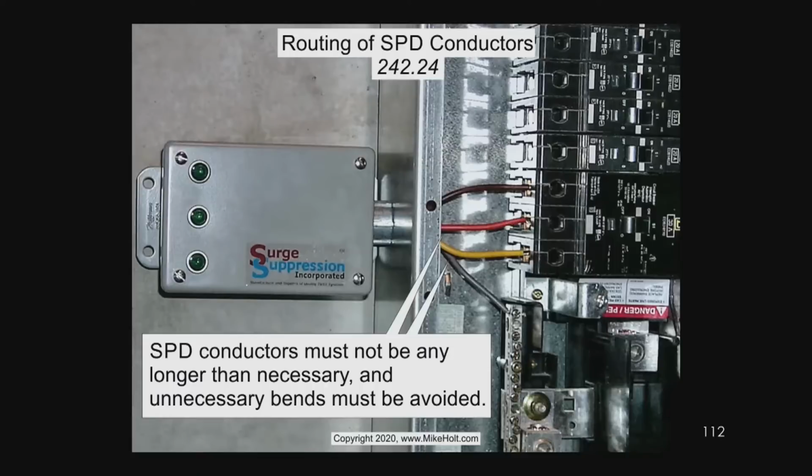Well, you're able to create more current, more voltage drop each stage to get the voltage down. And the last thing is routing of the conductors. 242.24 says surge protection conductors must not be any longer than necessary, and unnecessary bends must be avoided. What's the deal there? Sure. So two things. The main thing, you don't want the voltage drop that is occurring because of the surge protection device to be all across the leads of the surge protection device, because then you're not affecting the load.